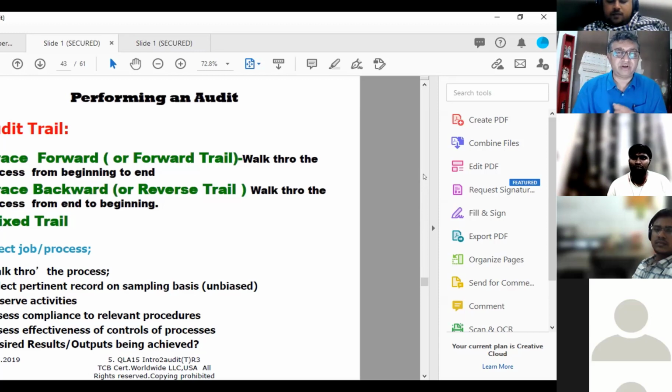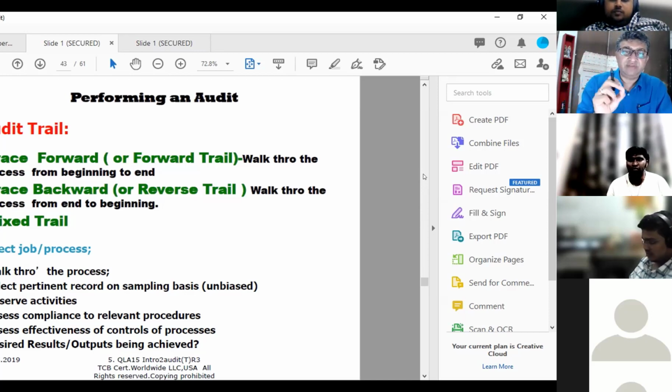Can you show me a picture of the event? No, this is not your intention to find. There is evidence of hydrotest done. There is possibly a chart maintained. This is the evidence. This is what it means that it is hydrotested. So objective evidence should be evaluated objectively to find the degree of conformity against a requirement. That's audit. So never forget this definition because it itself includes all your role, responsibility, and processes for the audit.